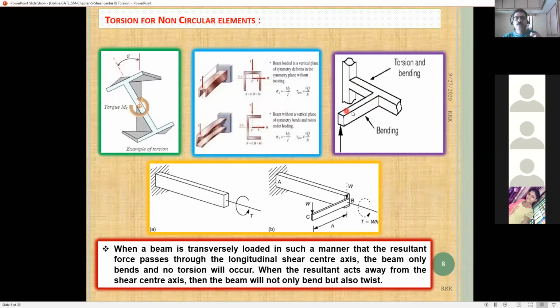This beam, suppose this cross beam is there. I apply the load. It will try to bend, right? So up to this beam, it is only bending. But if you see, due to this load this beam undergoes torsion. See, because it is connected here, it will try to rotate at that point. Because the load is here. Please remember, load is not here, load is here.